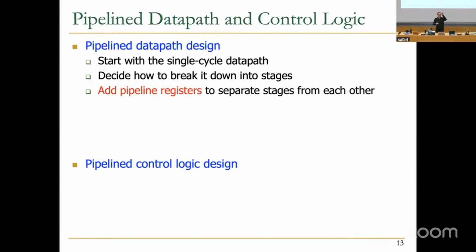So each stage has a pipeline register that's the output of it, which is the input of the next stage. During the clock cycle, you do some processing in that stage, and the contents of the register doesn't change. Only at the end of the clock cycle, at the rising clock edge, if you remember, we update the contents of the pipeline register such that the instruction in the previous stage finishes the previous stage and moves to the next stage. Does that make sense?